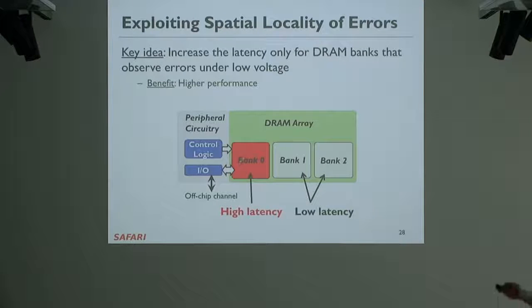And once you change the voltage only here, you can basically have different voltages for different banks and operate the different banks at different latencies. Of course, these increase the complexity in the memory controller. Right now, the memory controller needs to have different timing parameters for different banks. But that's how we explore new ideas in simulation again.